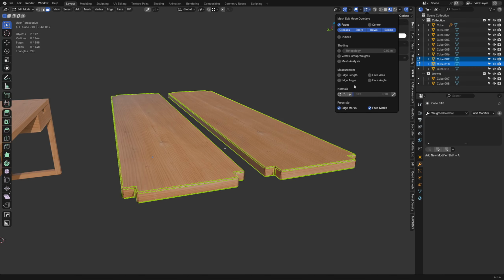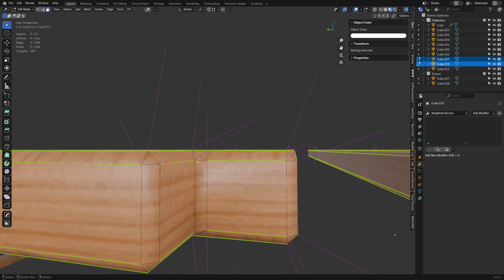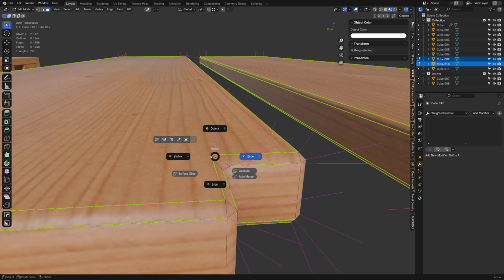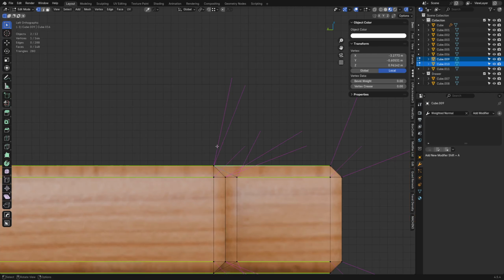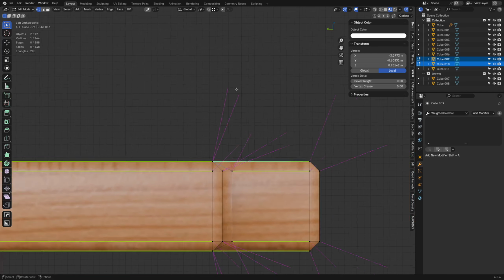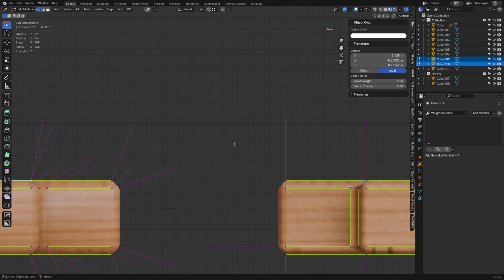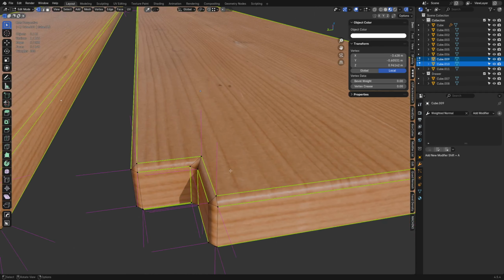And in edit mode, you have a preview here for split normals right there. Bump up size if you want. Okay. This is what controls our shading, right? So when we shade smooth, you see these ones here, they're kind of going out. These little, like this one in particular. As we move our mesh, this is how your shading's computed. This one's going kind of up and out that direction. And so is this one, right? It's doing the same thing, those two. Over here, when you weight your normals at 100, they're doing this. Okay. So it's a little bit different.